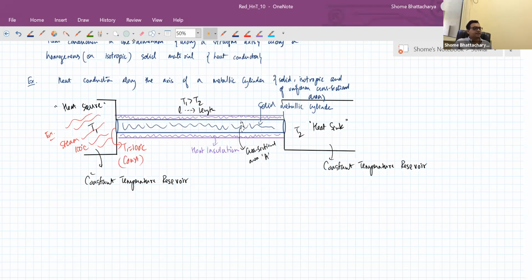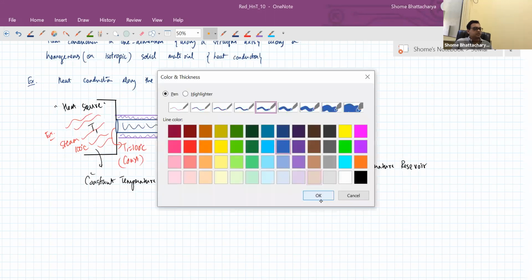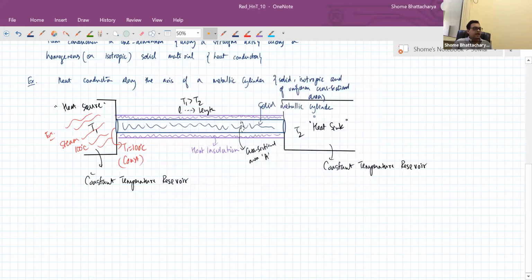And in the same way at the other end, we could pack ice at 0 degrees C. As the incoming heat by conduction melts some of the ice, we remove the water formed and keep stocking up a fresh amount of ice, packing it so that it remains at 0 degrees C. So ice at 0 degrees C. This is one practical method at the laboratory level to maintain these constant temperature heat reservoirs.